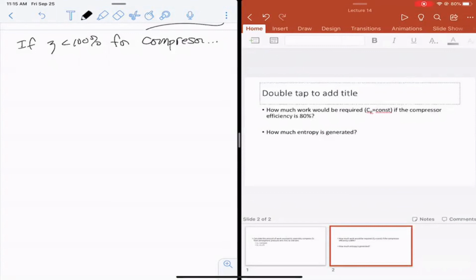So if we have an adiabatic, perfectly reversible compressor, we're not generating any waste heat at all. And that's the thing that allows the efficiency to be 100%. Everything that you're doing to the gas, all the work, is going towards the compression, not to generate heat. And remember that just because the temperature goes up does not mean that you're adding or removing heat, right?